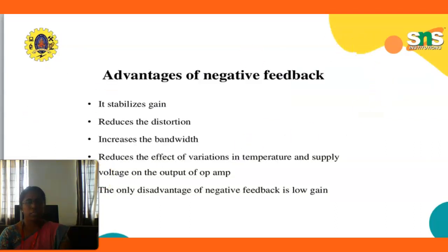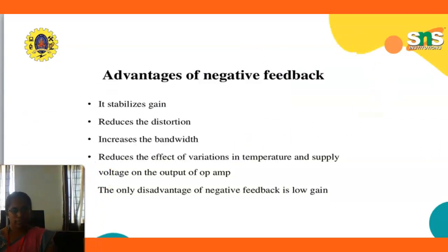So these are the advantages of negative feedback. It stabilizes gain, reduces the distortion, increases the bandwidth, and reduces the effect of variation in temperature and supply voltage on the output of the opamp. The only disadvantage of negative feedback is low gain.